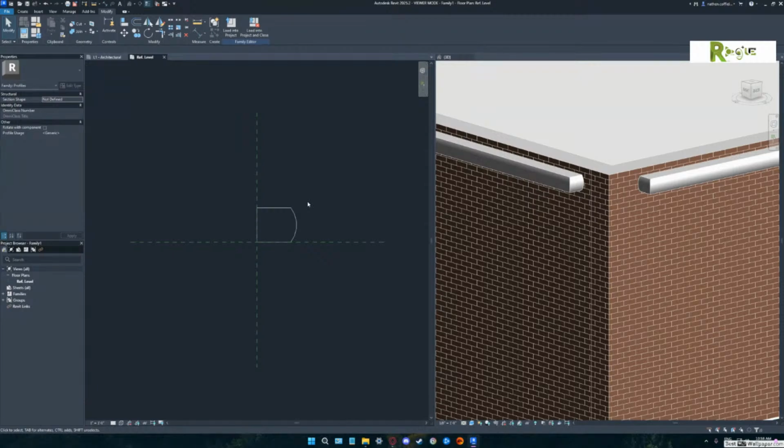Okay. Now, if you wanted to put more detail on there or change this guy's shape a little bit, do you see how we just have to make a change to the shape? And when we load it into the project, it updates it automatically. That's where you would have had to, in any other software, go back and reapply that sweep or make a new sweep or adjust the sweep in a different way. This is where building with these profiles is so beneficial.